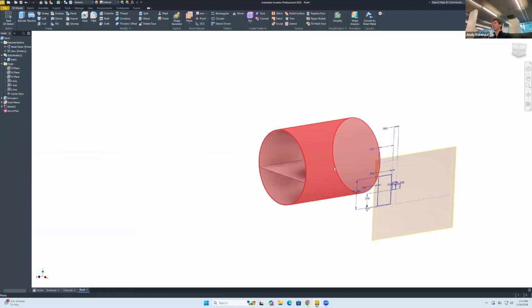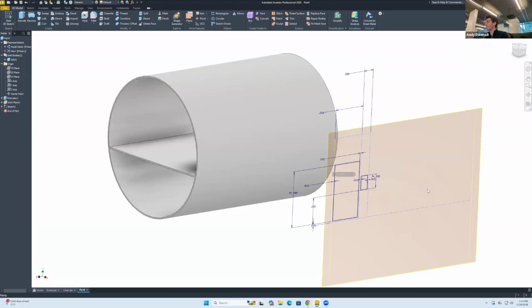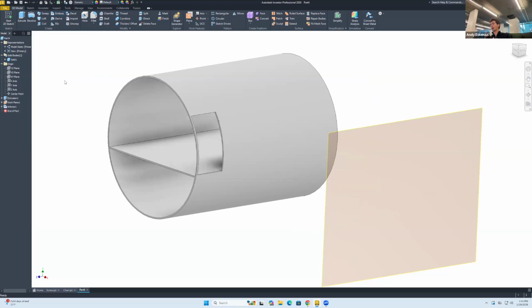I'm going to introduce the last command that we'll learn this year. It's called wrap, which is how you make the Diet Coke. So what does this do? Well, we go here to, it's called emboss, wrap, it's in SolidWorks. So for profile, I will select that rectangle. And I'm gonna say that I want to extrude like that. And let's see what it does for a second. I'm gonna click OK. So it just cuts through.